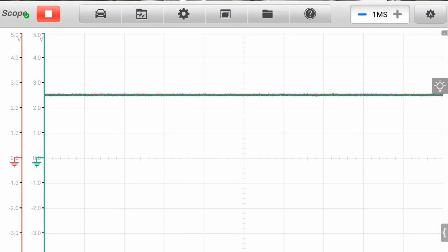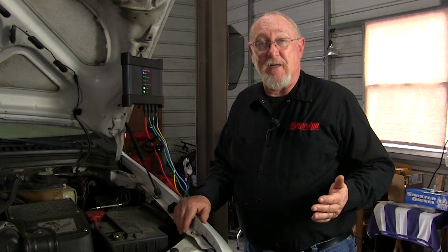I don't really care though what module is sending or what module is receiving or even what the message might be. I'm more concerned about the quality of the signal. If I see any abnormalities in the pattern, I'll need to focus my troubleshooting there first. Since I'm dealing with the loss of communications with just one module, my troubleshooting focus is now going to center